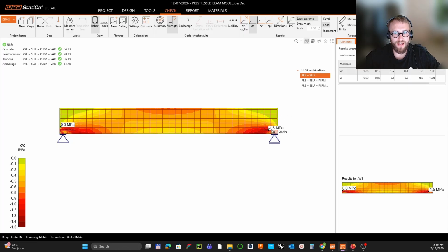But the critical stress under compression is close to the level of the support, where we can expect some discontinuity, clear discontinuity regions, where the Navier hypothesis is not valid at all, and the solution that is coming from the beam is not basically capturing those effects in these discontinuity regions. So we will be solving the area here.